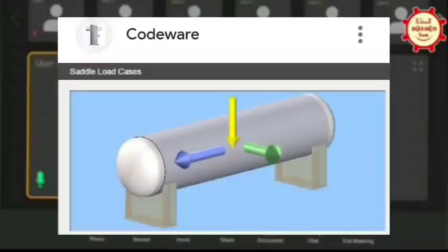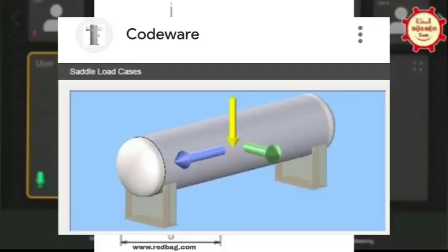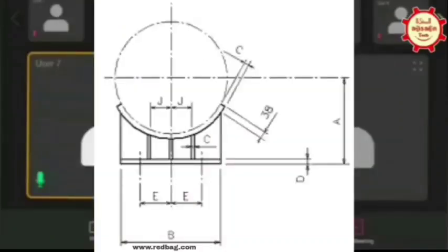It is the same as when we use the bundle pull out condition in the tube dialog box, or we use force and moment. Both are different, but we are putting the same load on the fixed saddle. With one condition in the tube dialog box, it will fail. If we provide force and moment, it will pass.